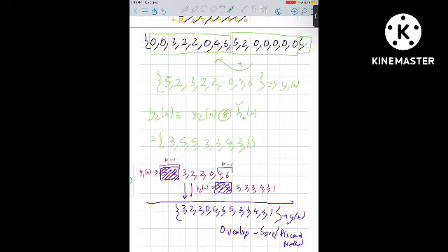Remove the first m minus 1 samples from each block and fit the rest of them. So let's see how they fit: 3 2 2 0 4 6 5 3 3 4 3 1. So this is your final output. This is your yn. So we have done the overlap save or discard method.